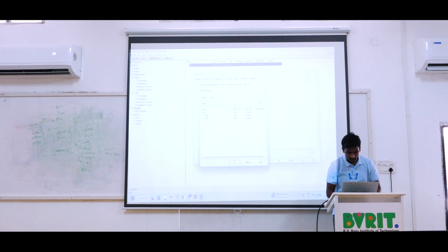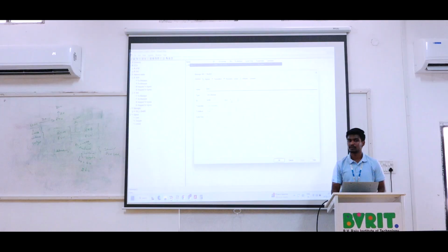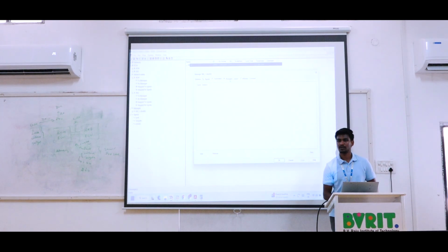Just now I added the lock, using the control button, unlock and tailgate. So now 3 signals are added here. You can check here, 3 signals are added. Then give Apply and it will be okay. Now you can double click, and you can see that the DLC is automatically adjusted, because the 3 bits are compressed under 1 byte. Now we can go to check signals, and the transmitter and receiver are not mapped, so that column will be empty. Next we go to layout.